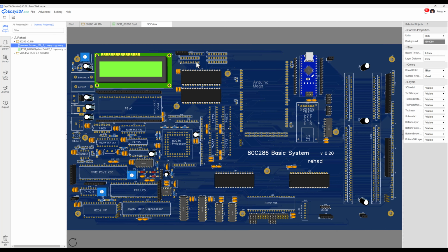So if at some point I want to slow down my clock, I can flip to my external oscillator and use my other card temporarily. I can also then reconnect through these headers all of those different LEDs and do a slower debug if and when I ever decide to do that. So the functionality is there. It's just I'm not going to take up space on the board itself to do it.